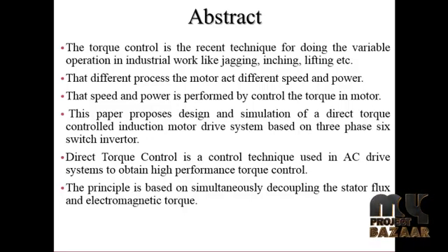The speed and power are controlled by controlling the torque in the motor. This paper proposes the design and simulation of a direct torque controlled induction motor drive system based on the 3-phase 6-switch inverter. Direct torque control is a control technique used in AC drive systems to obtain high performance torque control. The principle is based on simultaneously decoupling the stator flux and electromagnetic torque.